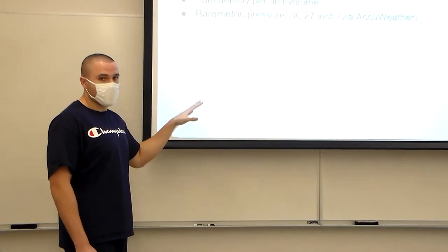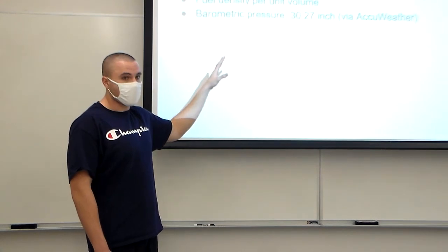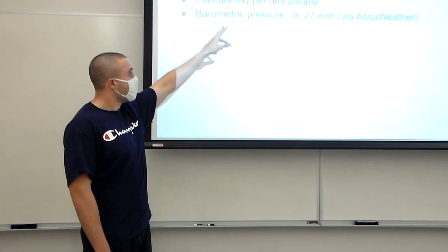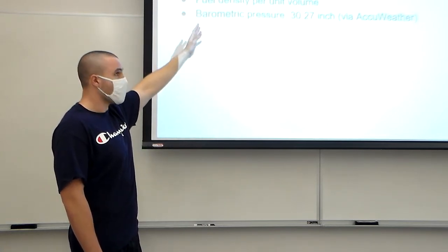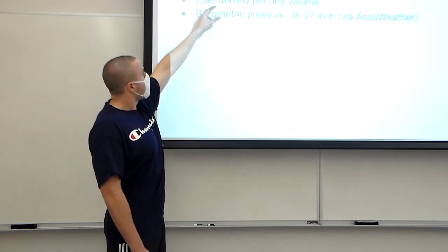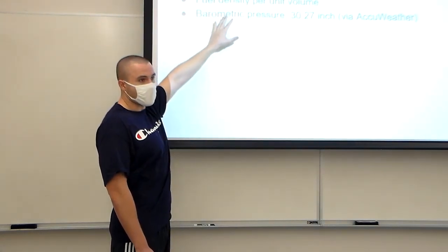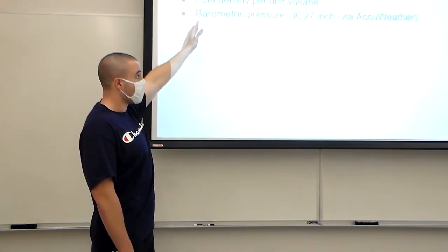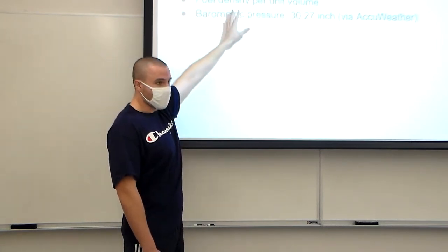So other important operating parameters before you actually start the experiment is you want to know your fuel source. And Richard told us he basically had like a homemade backwoods 50-50 diesel kerosene split of fuel. And so we weren't exactly sure what the ratio was or even what type of fuel it was. And so as a result, you want to know your fuel energy per unit volume as well as your fuel density per unit volume. But since we had some homemade thing, I didn't exactly know how to go about calculating it because I didn't think it'd be as simple as, add the 2 and that's it.